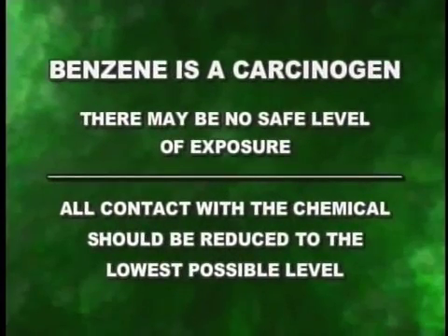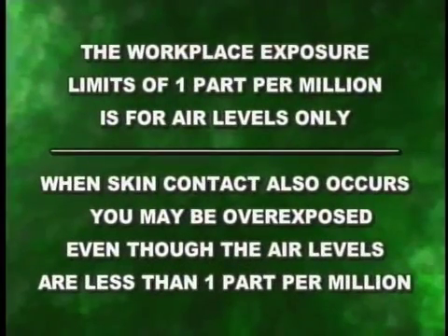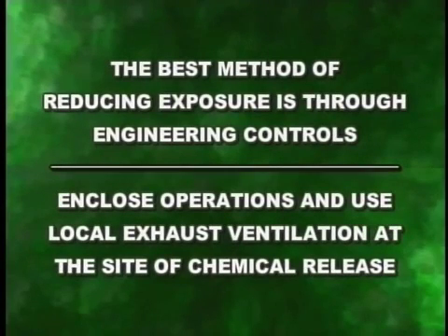Benzene is a carcinogen, so there may be no safe level of exposure. All contact with the chemical should be reduced to the lowest possible level. The workplace exposure limit of 1 part per million is for air levels only. When skin contact also occurs, you may be overexposed even though the air levels are less than 1 part per million time-weighted average. The best method of reducing exposure is through engineering controls.